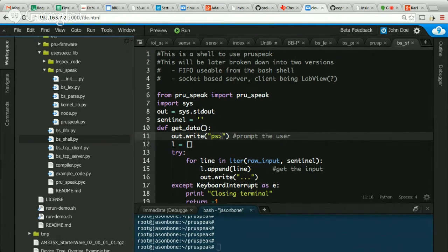And it's always able to continue to take additional direct commands, and that's what provides you with the ability to update variables and do communications with it, right? So you can look at the status of a variable or write to a variable, and that provides you ongoing communication between the ARM and the PRUs.